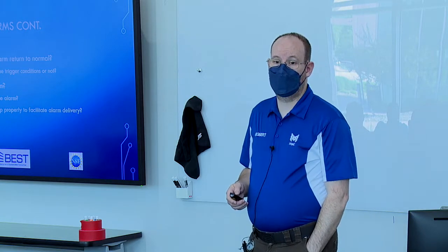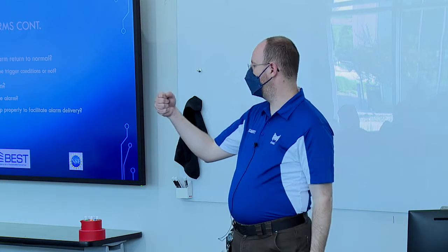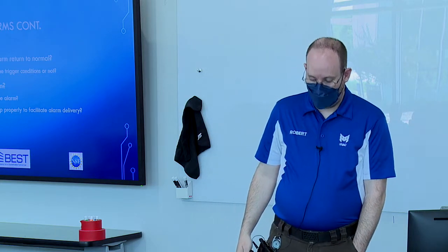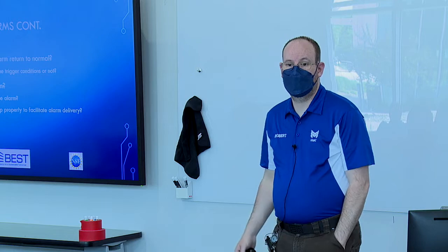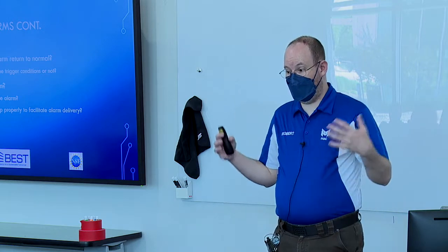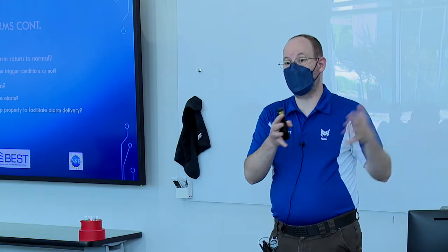I like the service side of it when you go to replace the static pressure transducer and you don't buy like for like, and then all of a sudden you can't open the doors in the building. Ain't good controls. Because your range is no longer correct. Yep. And it's largely indicative of we've got so much work and so few people.